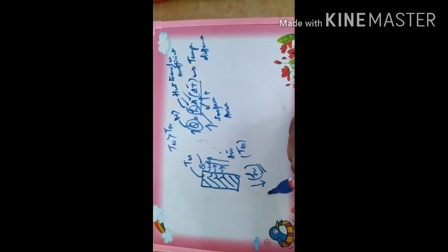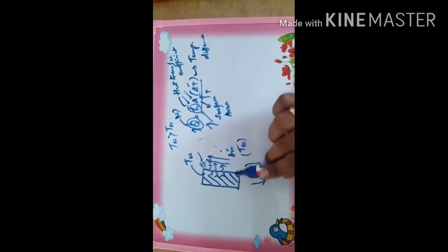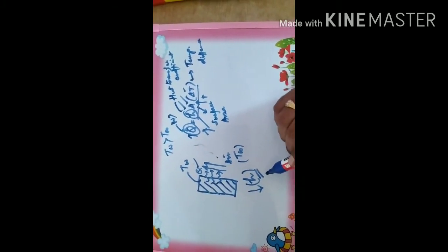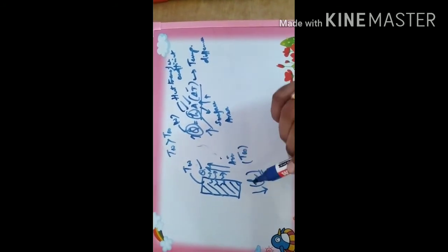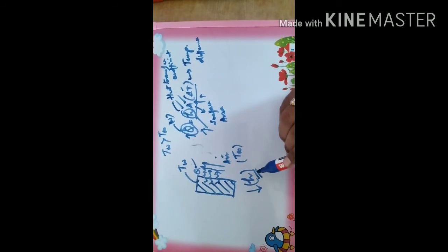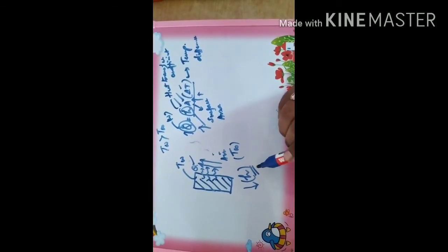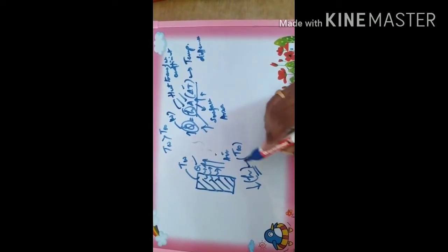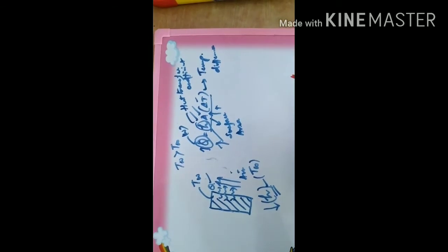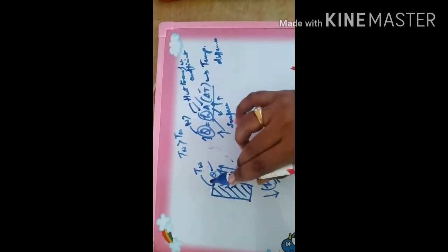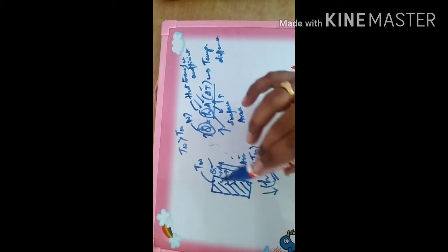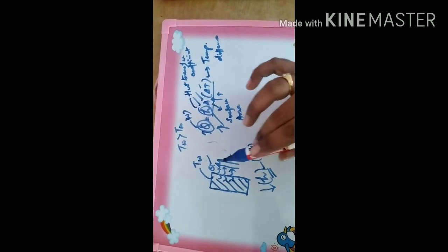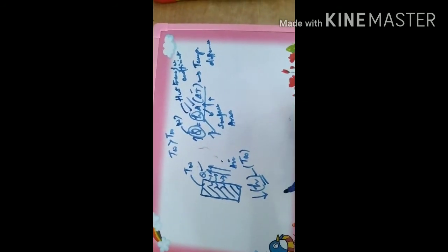So we want this value to be increased. It is practically possible to increase the value of h by increasing the velocity of the air, but it is not sure that you can increase it to a larger value. So there is some limitation for this value of h. You can increase it only up to a certain point, by changing the properties, by increasing the surface roughness or the surface finish, as well as by increasing the velocity.